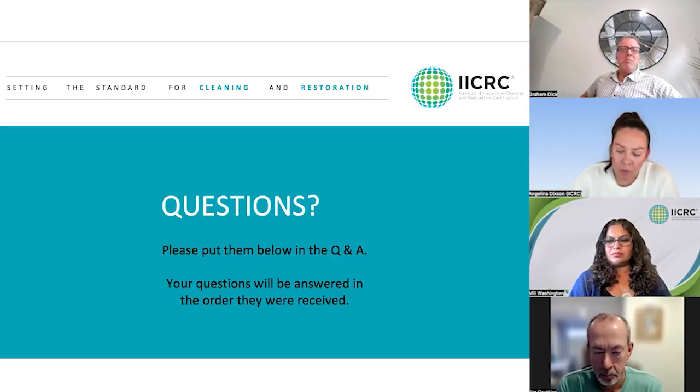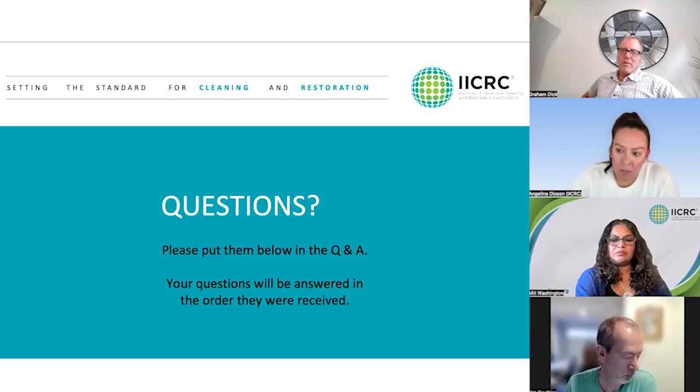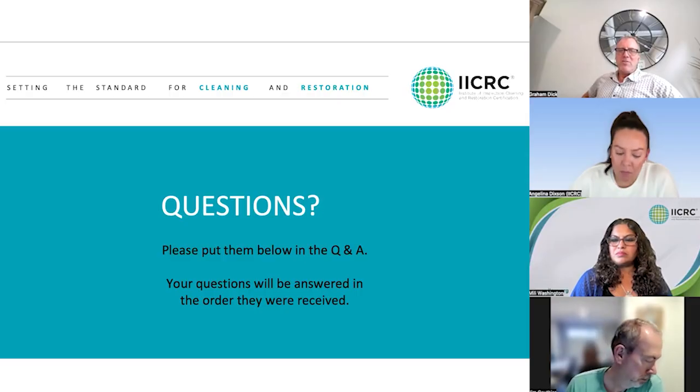Most vacuums these days are going to give you a pretty decent result, as long as they're maintained and working to manufacturer's spec. If you want better, then you have to go to HEPA. And just because it has a HEPA filter doesn't mean that it's certified HEPA. What that means is that it's been performance leak tested to prove that all the air flowing through it passes through the filter.